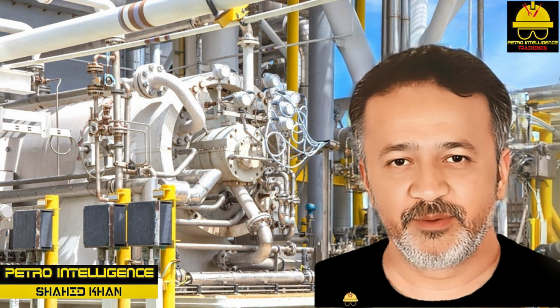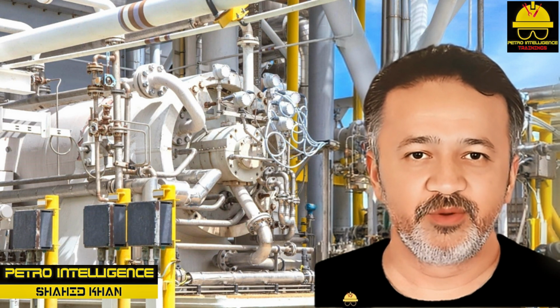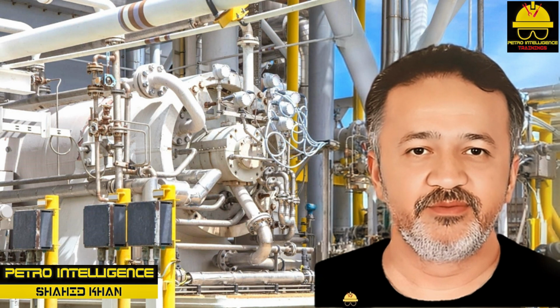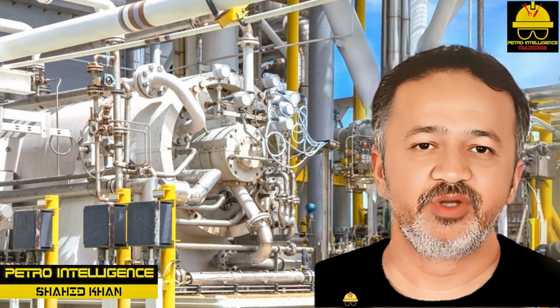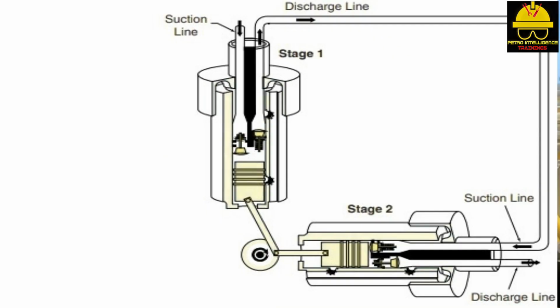Single-acting multi-stage compressors. A multi-stage piston compressor has 2 or more cylinders. The first cylinder usually is referred to as the first stage. 2-stage multi-stage compressors as shown in picture discharge from the first cylinder into the suction line of the smaller second cylinder. In a multi-stage compressor, flow rates usually are low and overall pressure is high.